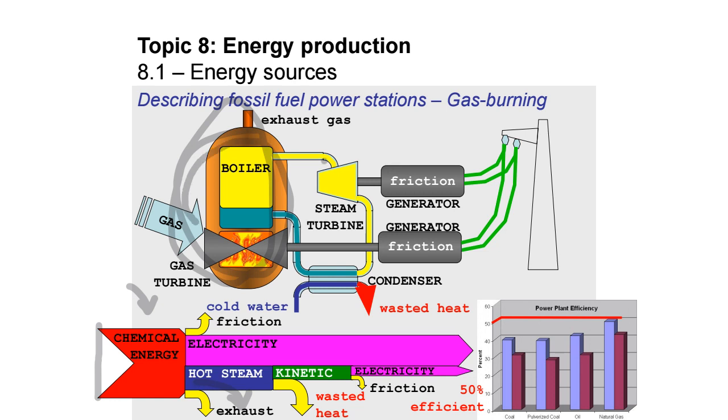The steam as well, and this is interesting, is worth considering. Your steam, so you're heating up the water, which makes steam, and then the steam goes through the steam turbine, spins the generator here, and then cools down, basically loses all its energy. And as it loses its energy, it condenses, right? It comes down here. And it's actually forced to condense and to go down to a much, much lower temperature.